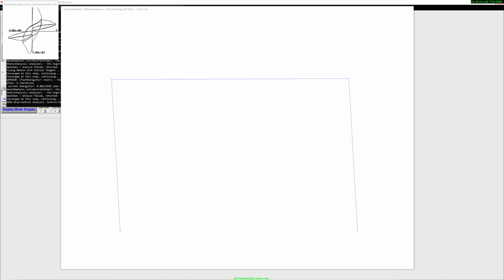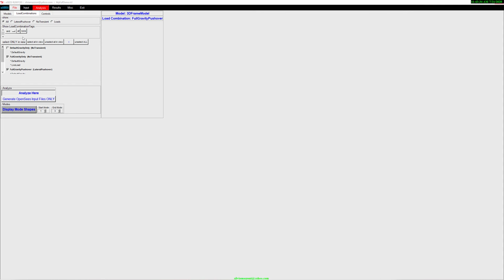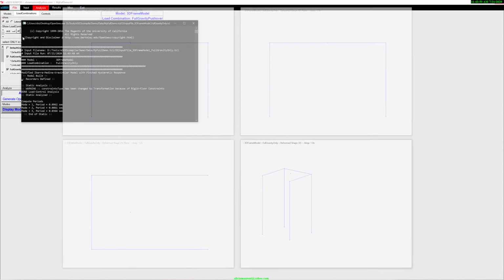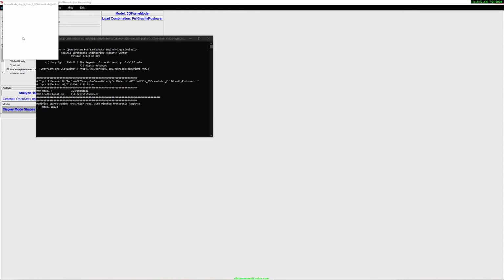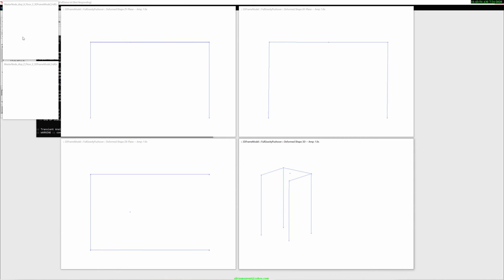The time history analysis is nice because you can actually watch the time history. So maybe I will run that analysis next. It's done. Now it's processing that analysis. It's going to take all the data and reformat it into new files that are a little bit easier for the program to read in the post-processing visualization. Now it's going to grab it in the 3D. That's a lot faster. And now we start our pushover in 3D.